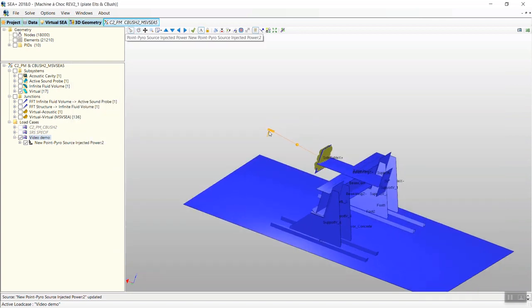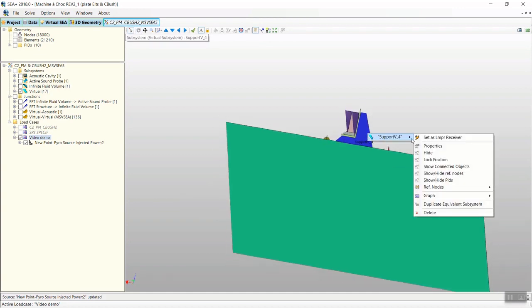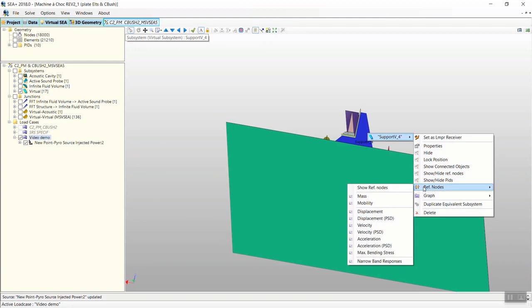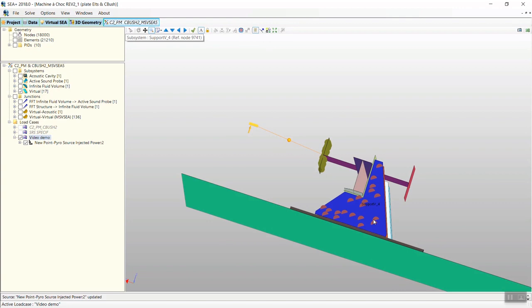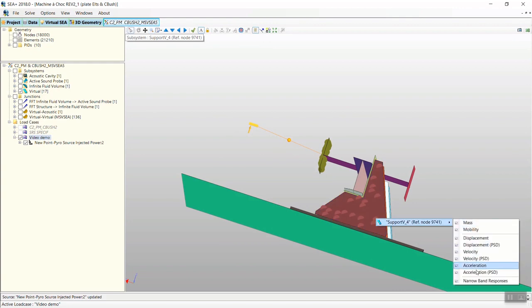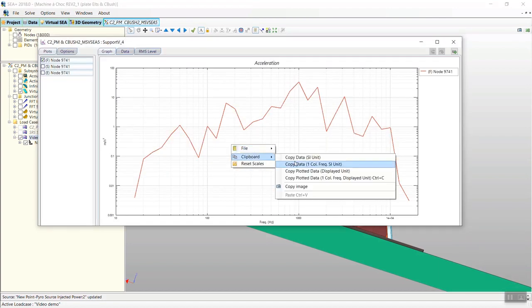And then these data are roughly corresponding to what I measured in test. In that case, there is a test at a distance, a reference node, and we have one node near the accelerometer M8, and then I can compare the acceleration at that point with the measurement at that point in terms of RMS acceleration.